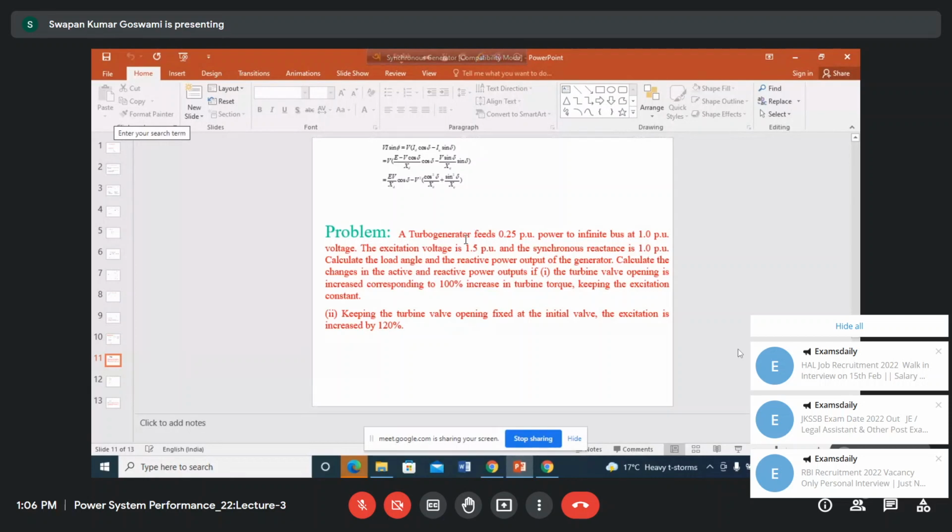You know that for power system calculation, for power system analysis, per unit system is very, very useful. Why? Because due to the presence of transformer, there will be change in the voltage level, and as the voltage level changes, current also will change, impedance also will change. This creates difficulty in continuing calculations in power system because there will be so many voltage levels in power systems.